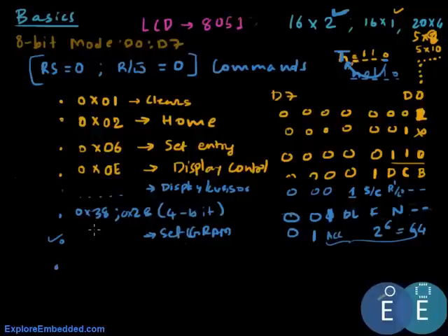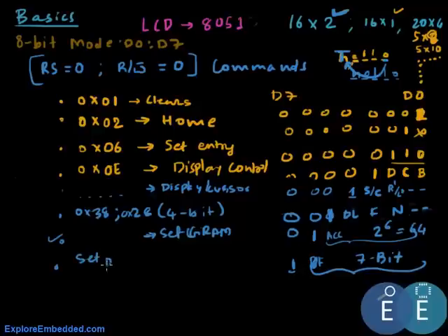Now the next command would be, and obviously the last command, so the one gets here, and this bit is called the busy flag. Now no, sorry, this is not the busy flag. Since this one gets here, we have a 7-bit address, and with this we actually display the contents of the DDRAM, or we set the DDRAM address.